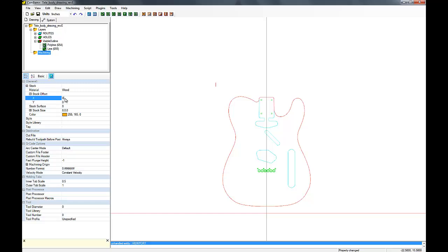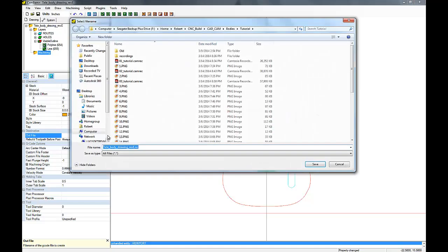And we'll set the stock offsets. This is in relation to the X and Y axis. And you see I put in -9. That's not right. I'll fix that in a minute. And the stock surface, I start at -1, which means it's 1 inch below the 0 on the Z on my CNC machine. That's just how I operate and my machine is set up.